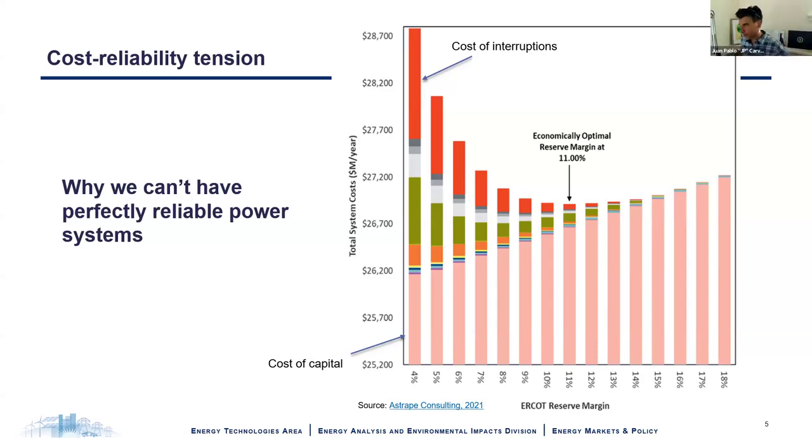Yeah, the capacity credit of resources is going to define what the percent is and how you meet it. So in some cases, a grid that has a ton of solar and wind will have a huge reserve margin. It doesn't mean that it's more expensive. It just means that you need to secure that gap because these resources will fluctuate more.